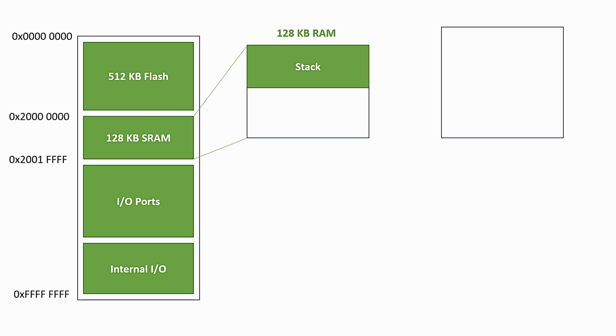And in the ARM Cortex-M processor, we have 32-bit data addresses, and the top of the stack is allocated right over here in the lowest memory location, and it is pointed to by the pointer called the stack pointer. In register terms, this is also called R13 in the ARM Cortex-M processor. And the dedicated stack memory size can be taken as 4096.